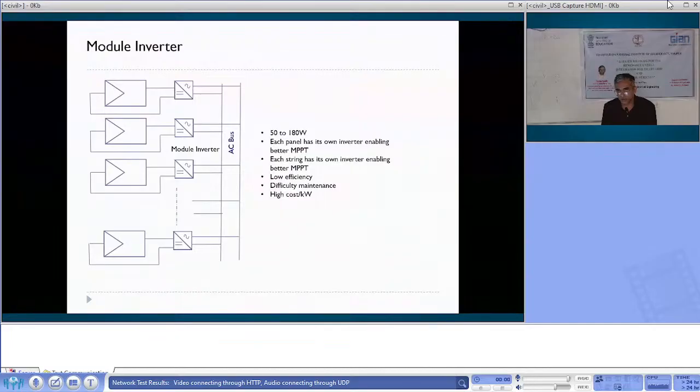Fast tracking is required when you are installing the panels on a vehicle. Then you require very fast tracking because a shadow comes and immediately goes, as the vehicle moves from the unshaded to the shaded area. For a stable system, you may not require that much fast tracking, but if it is fast, it is good.